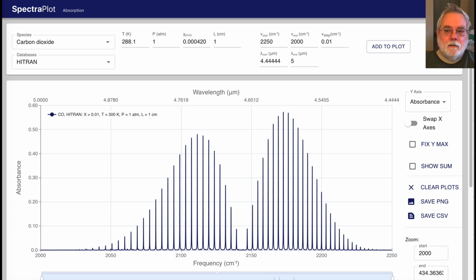We can set very large lengths, such as 100 kilometers. However, beware, the model is constant temperature and pressure. This model does not implement Earth's atmospheric profile. There is no gravity. If you set the length to 10 kilometers, you are not getting the result for 10 kilometers of atmosphere. Think of the tube as horizontal, not vertical. The default length is 1 centimeter, but I am changing this to 100 centimeters, 1 meter.